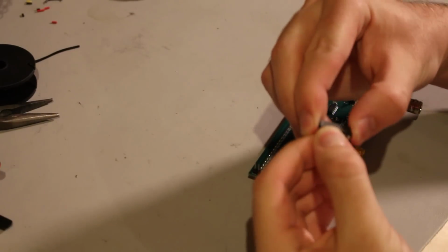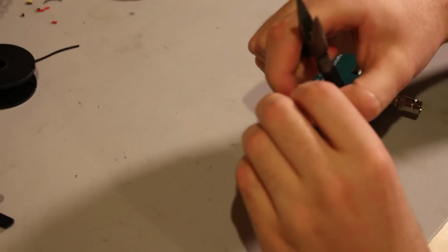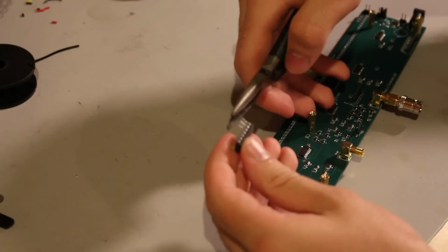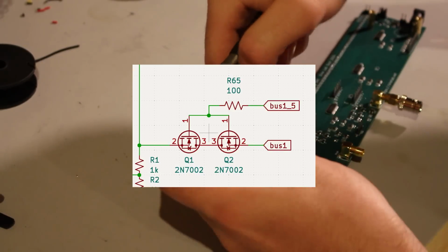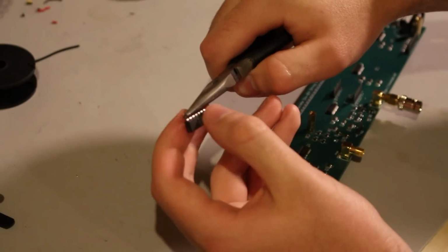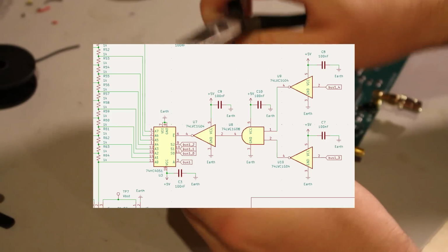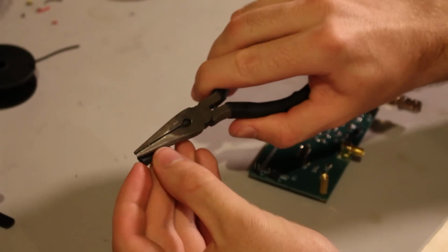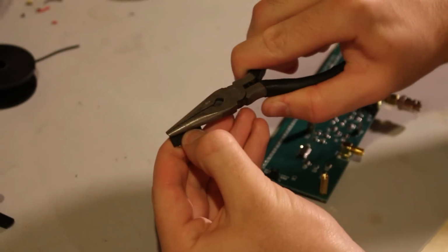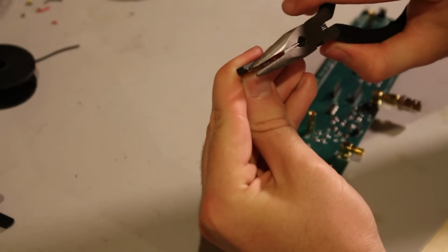Well, almost. Somehow, I overlooked what happens when the highest switch on bus 1 is activated in the DAC. You see, when bit 5 is active, so is the switch, which is correct. But the part that I overlooked is that the lowest multiplexer doesn't take this into account and just sees the 0 code. This means that the highest and lowest switches are active simultaneously when we are at the full scale code for bus 1. Luckily, it was a somewhat easy fix.